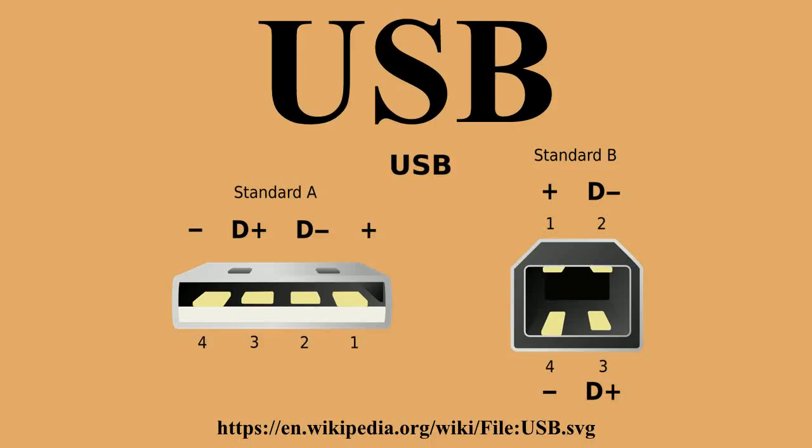USB 3.0 defines a new superspeed transfer mode, with associated new backwards compatible plugs, receptacles, and cables. Superspeed plugs and receptacles are identified with a distinct logo and blue inserts in standard format receptacles. The new superspeed mode provides a data signaling rate of 5.0 Gb/s.